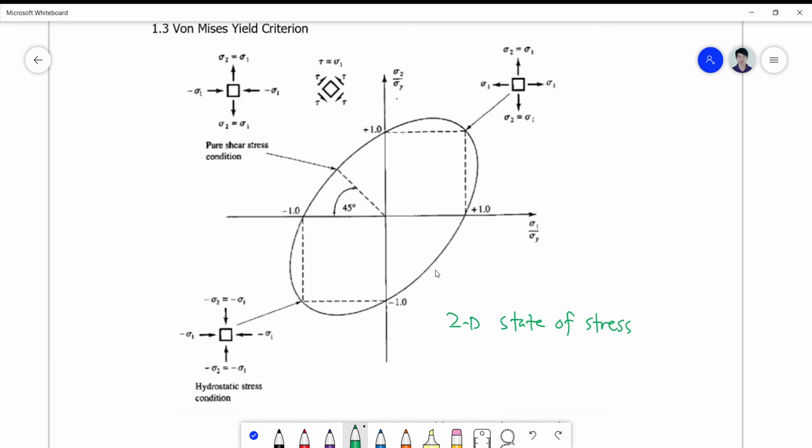and define the elements in terms of both hydrostatic strain and distortional strain. So which means that the total strain energy we are considering here is contributed by both hydrostatic forces or pressure and distortional forces or pressure.